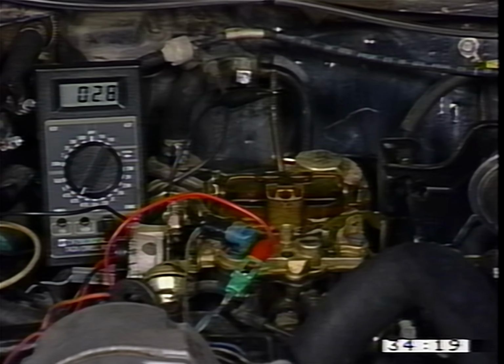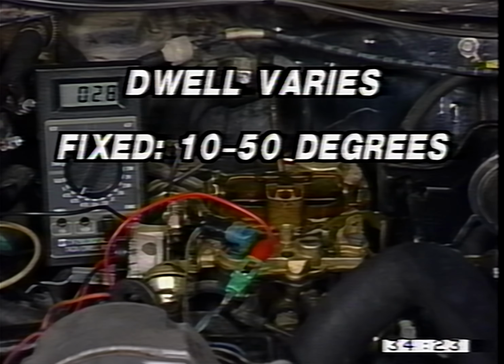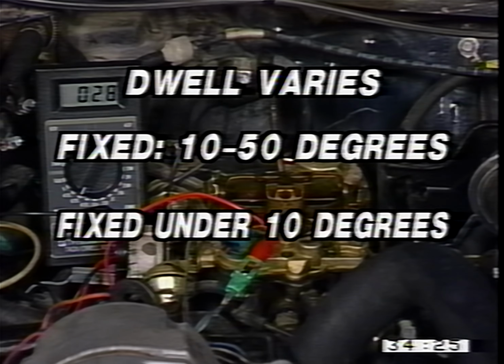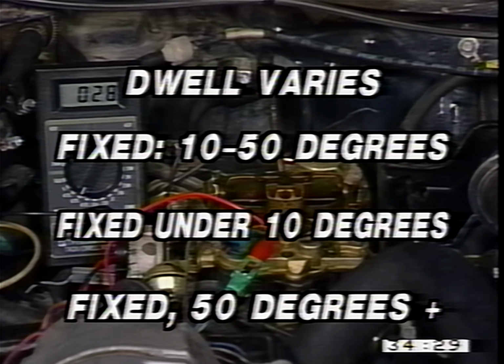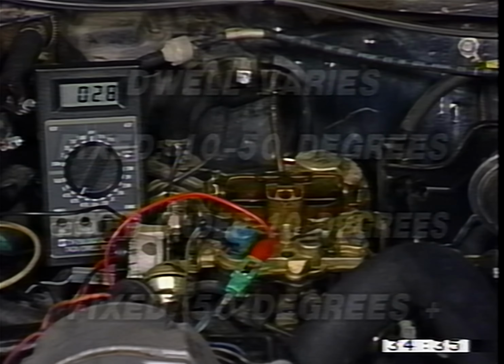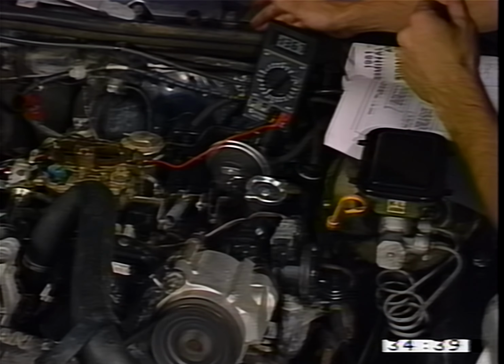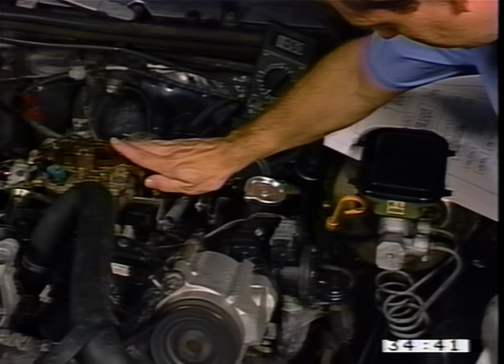At this stage, there are 4 possibilities. The dwell will vary. It will be fixed from 10 to 50 degrees. It will be fixed under 10 degrees. Or it will be fixed at 50 degrees or over. In any one of these choices, you'll be directed to diagnostic chart testing or to go on to Step 3. Step 3 directs you to check the dwell at 3,000 RPM.